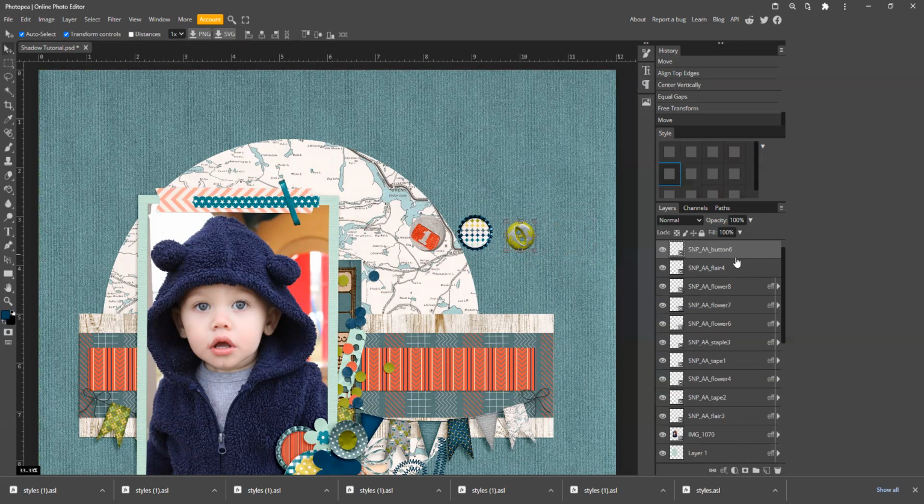layers by holding your control down and selecting the 3 layers that those items are on. Otherwise, you can select on the layer, hold your shift key down, and select them just with your mouse. So once I have all 3 of those selected, because they still are not exactly the same size, I'm going to center them vertically so that it just aligns their centers. Then I'm also going to select on the equal gaps or distribute here so that the spacing is the same.